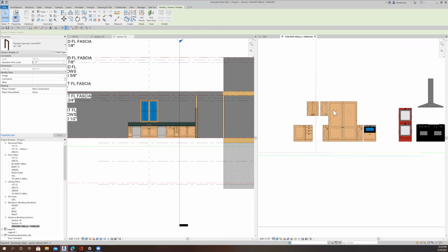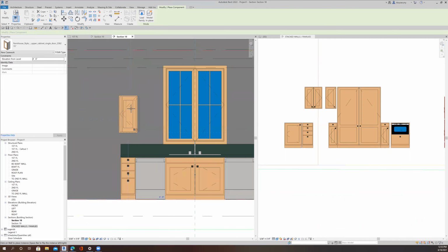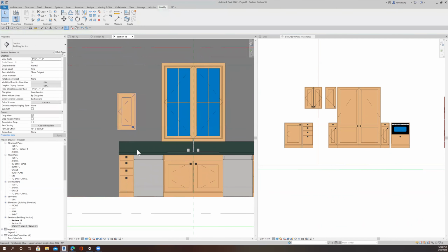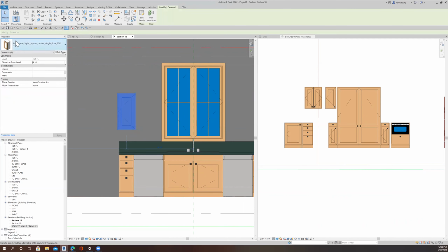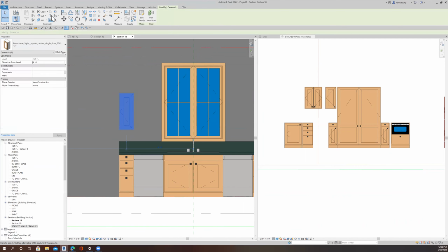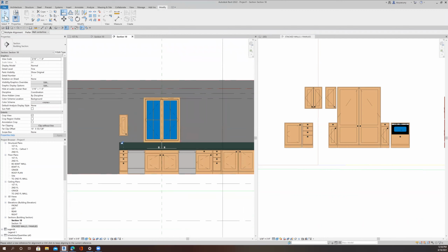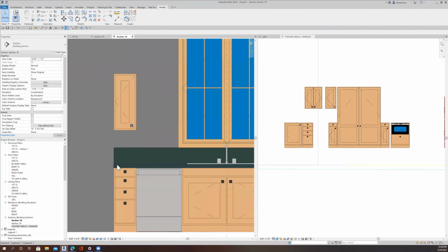Now we're going to put some upper cabinets in there. So this is going to be a single cabinet. All right. I think we said this doesn't work. Create similar. Come over here. Oh, look at that. Okay. All right. So now we're going to have to make a new height of window or cabinets. But first of all, I think that's a 12-inch wide unit, so let's do that. And then we'll center that unit on this guy so that they line up, okay? I like that.